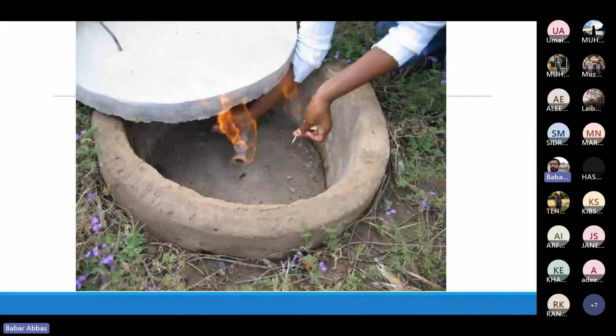So this is the output from a biogas digester, and you can check with the flame whether the biogas is generated or not. Similarly, you can check the quality of the flame, whether it would be effective for the utilization or not, like it would be offering the required calorific value, or it is not offering the same calorific value.